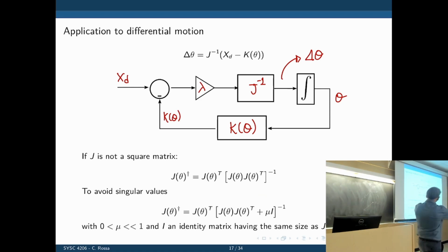So what is this doing? This is a loop that will run several times, and once you decide to stop, the result is a set of angles theta that will minimize the distance between the actual position of the end effector, calculated from that theta, and the desired position of the end effector.